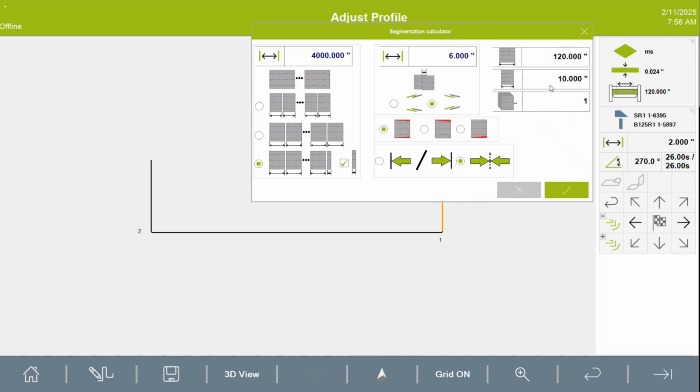Well, for this thing to taper and give you enough on a 10-inch blank, that back gauge has to really skew itself, right? It really has to be a severe disparity. And the limit for the machine is going to be 5 millimeters of disparity per meter of the machine.